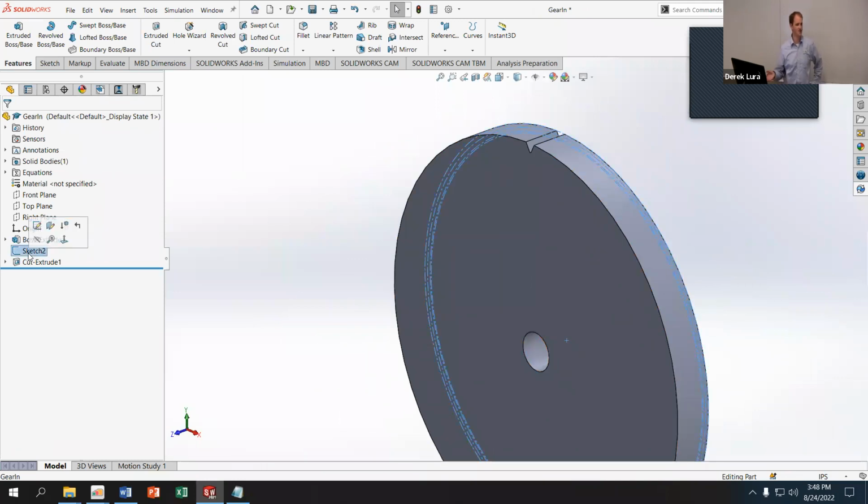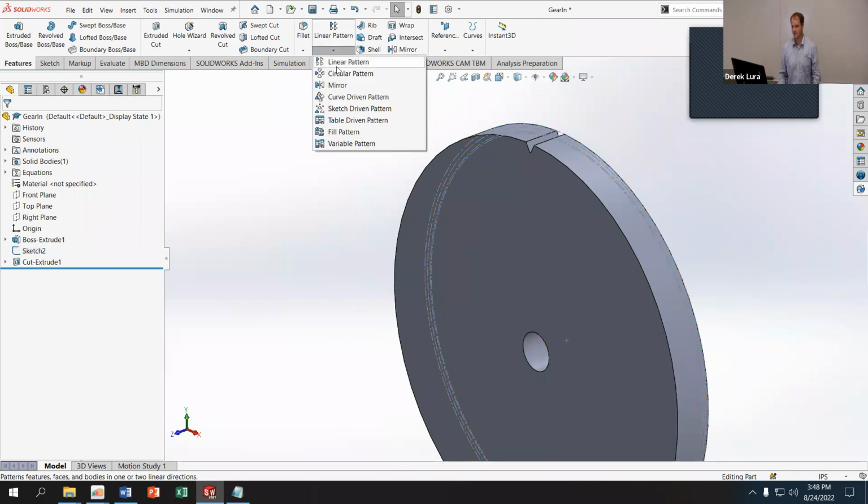I'm actually gonna leave mine shown because I'm gonna use that to drive the gear relation when I put this back into my assembly. Because now I've lost that exterior face that I was driving it with before, it's now too big. And so it's not gonna have the appropriate gear ratio. I need to use one of those center lines for my effective diameter to drive that. And we'll probably get an error when we go to do that, but we'll get to that in a second. All I need to do now is pattern this. So I'm gonna do a circular pattern.